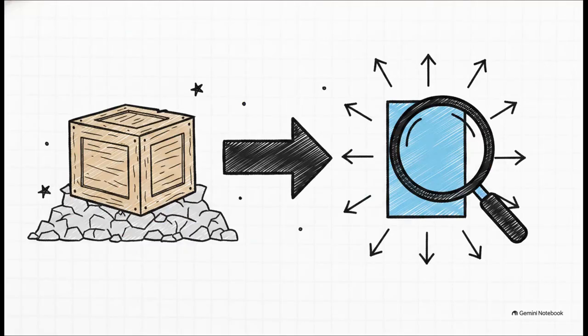Wrapping up this section, your main takeaway is to always start your analysis with an FBD. You've got to clearly separate the known external loads from the unknown support reactions before writing a single equation. A clean, accurate diagram is honestly an engineer's best friend and the secret to passing your finals.